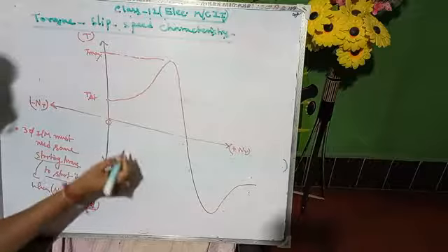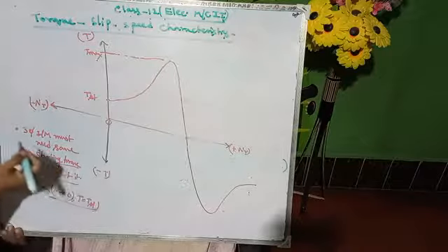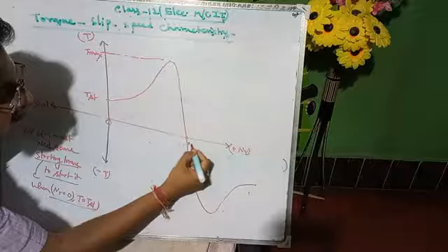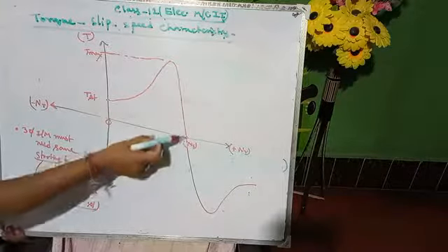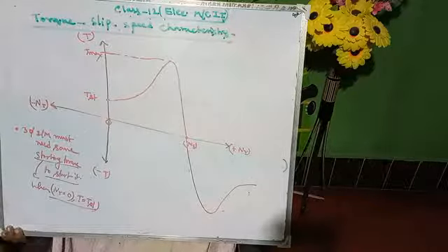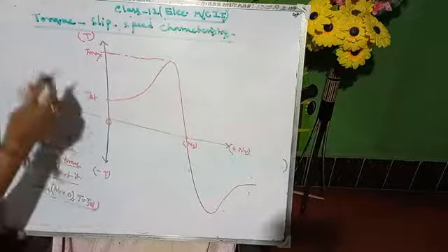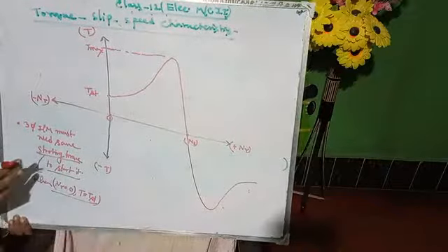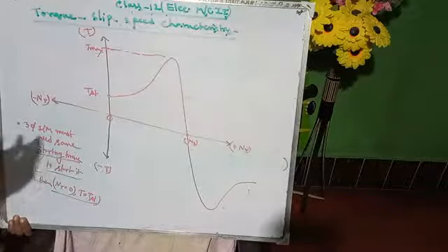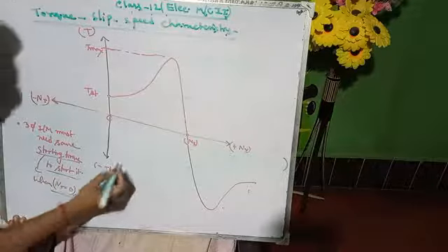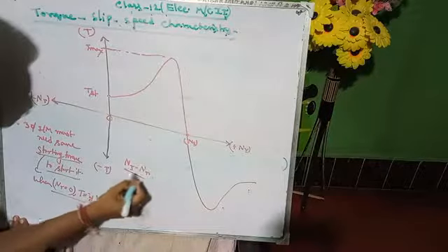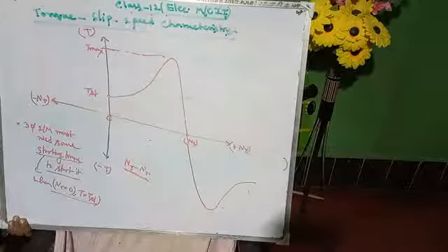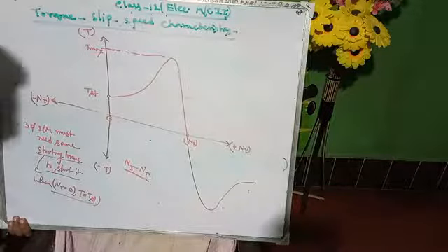So at this situation, ns is achieved. Okay, this is the ns. When ns is achieved, the torque will fall. Why? Because always remember, the three-phase induction motor works on the principle of relative speed between stator and rotor. In the next class I will write the operating principle, then you will get the ultimate answer.